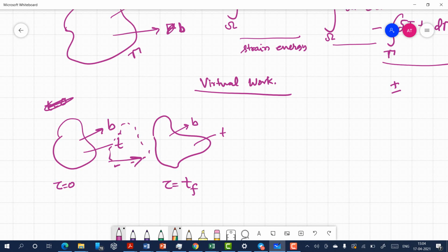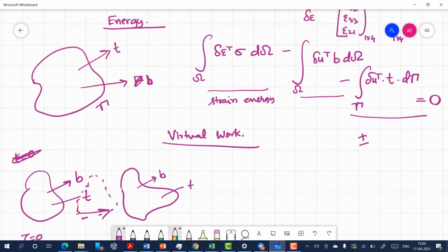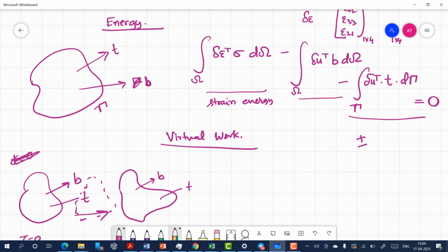Okay, and in an intermediate position, in the initial state, I can have some amount of strain which is already there in the material. So I can have some amount of thermal strain. Because of this strain, we have to take care of the initial amount of strain, and for that we need to modify the equation a little bit. So we just have to add the term for the initial strain. Let me do that here.